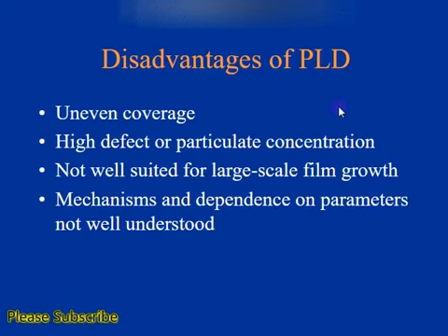and it is not well suited for large scale film growth. And this is the main big disadvantage of the PLD process, because in most processes and most commercial techniques we want large scale production, and if we want to deposit a thin film over a comparatively large area, then PLD is not a suitable technique, because for large scale, first of all you have to create a large chamber so that you can place your sample.